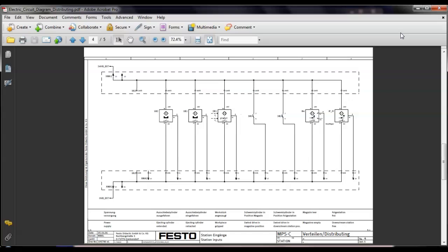So this is the input to the PLC. This is 0 volts. This is a minus something. That's a plus 24 volts across the top. This wire would be brown. This wire would be blue. This wire would be black. This single source.